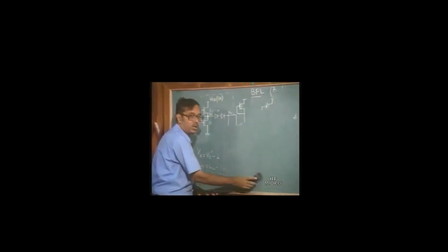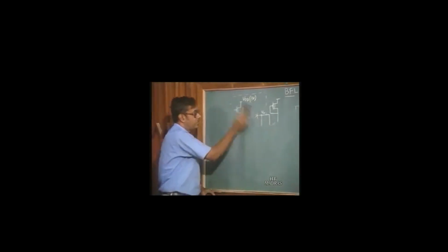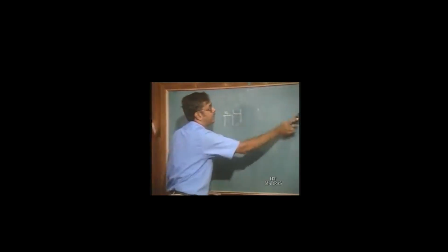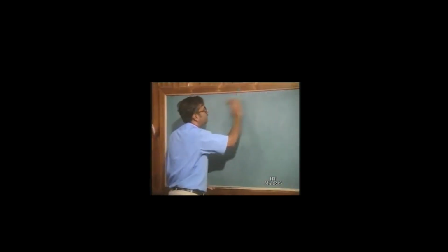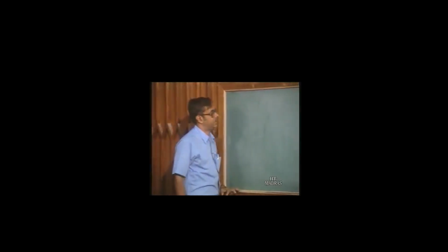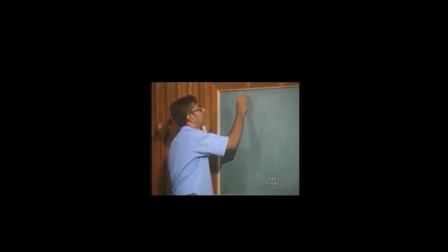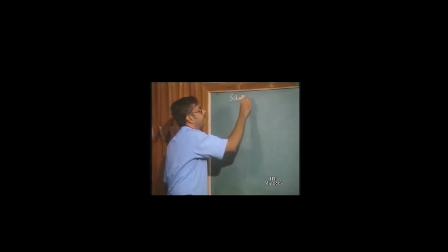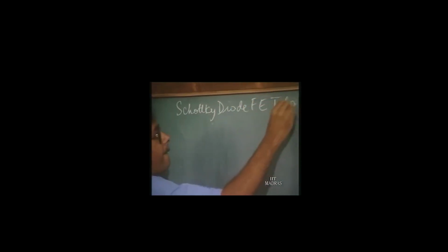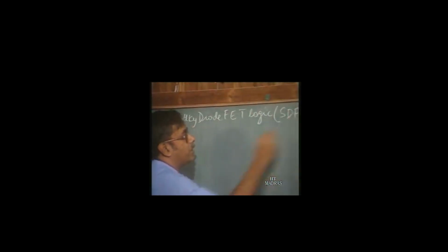I will just discuss one more logic family which also uses only depletion mode transistors, and which is also quite popular. This particular logic family uses Schottky diodes for logic operation, and it is called the Schottky diode FET logic, or SDFL for short. So, Schottky diode FET logic.